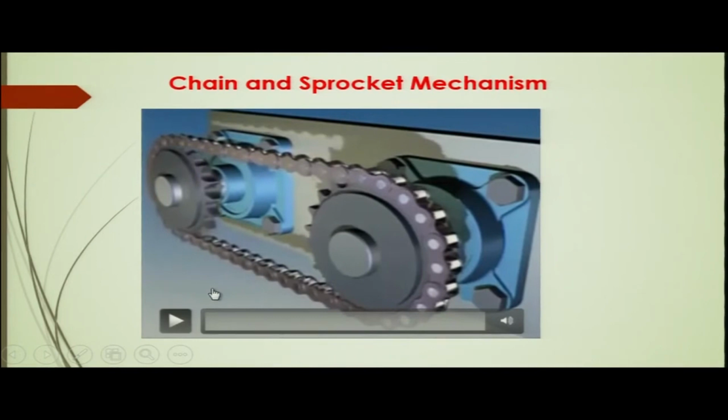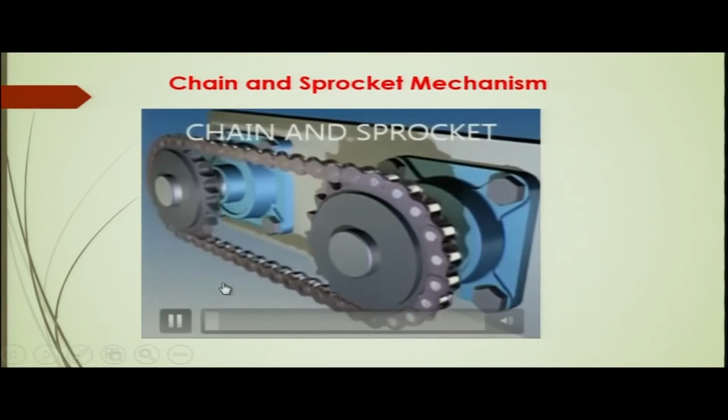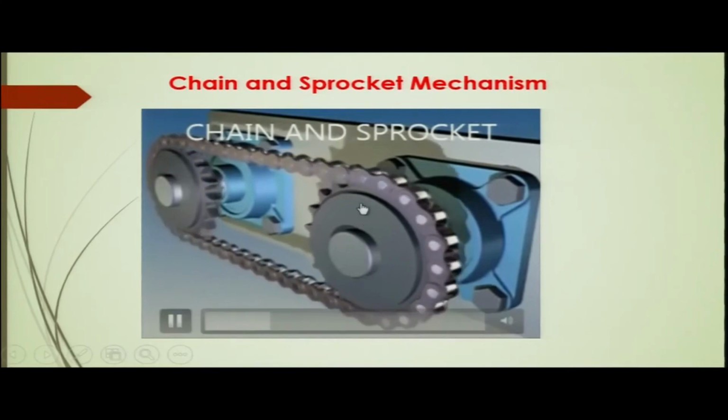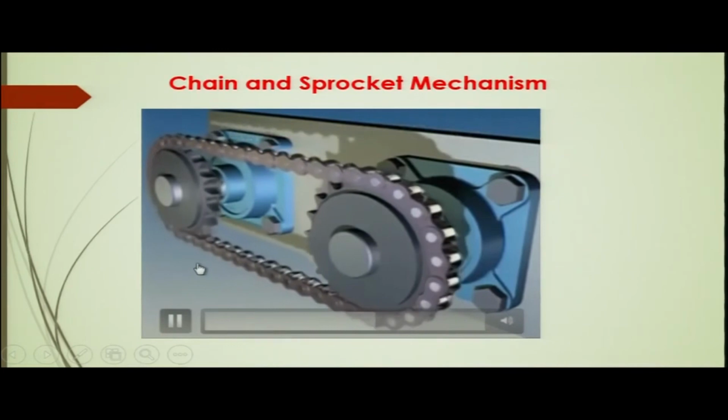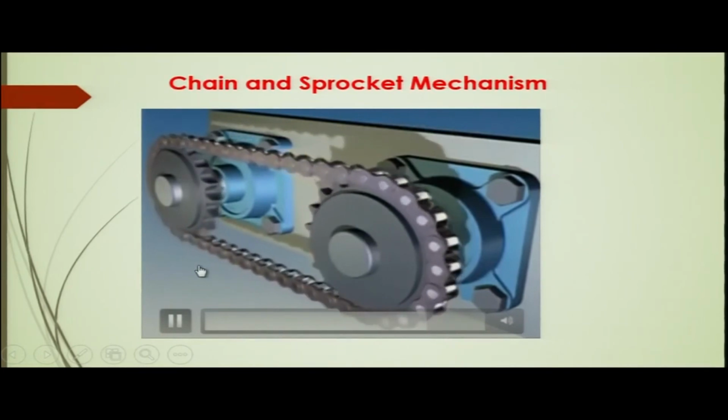And of course, these chains normally do not come as a cross chain like in the case of the cross belt, because of the construction itself; here it is almost not possible. Again, the transmission is made from the input shaft to the output shaft through the chain and the sprocket.